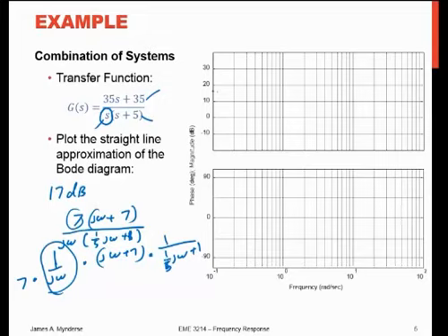for the pole right at the origin. At a frequency of 1, I get 1 over 1 times the square root of minus 1, or 1j. But the magnitude there is just 1. So this bare pole would normally pass through 0 dB at a frequency of 1.